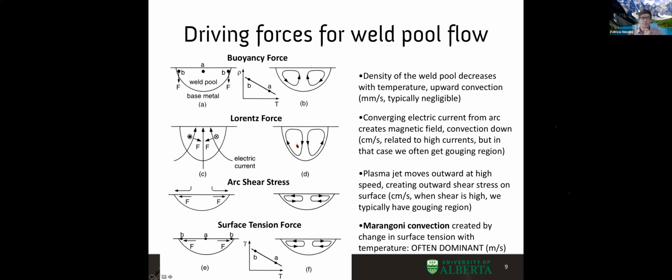At the same time, because we have an electric current, because it's TIG, we have electric currents going through the whirlpool, and those electric currents can also cause an electromagnetic force and have some sort of internal electromagnetic jet inside the whirlpool. And people calculated those. Lots of work, even in the 80s when computers were small and clunky and way less powerful than your phone, they were calculating those things. And they saw that these electromagnetic forces would be of the order of centimeters per second.